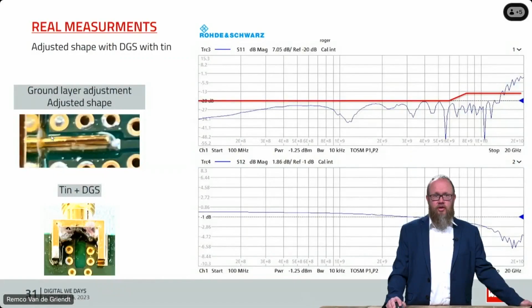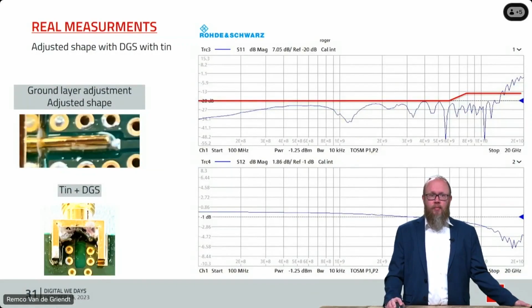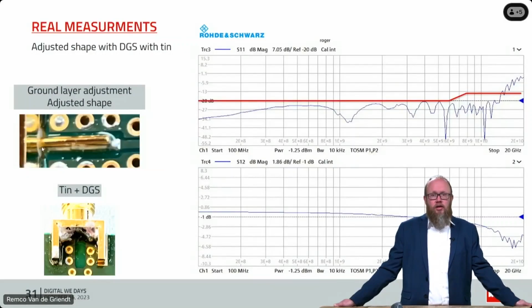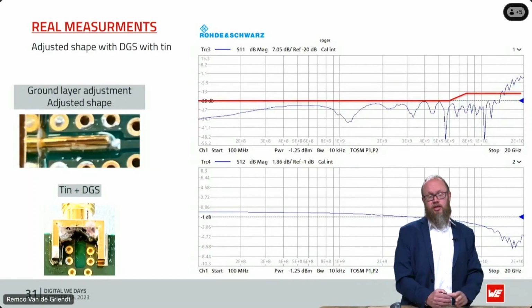I think this person means that if you look at it this way, it's not fully to the edge. If you look at the bottom side, we are already going to the edge to make sure that the grounding is okay. In this case, of course, you can still fine tune this solution. We are not covering the copper to the end of the PCB because that's a much more expensive way, and with this less expensive way, you can already make a lot of big differences there.